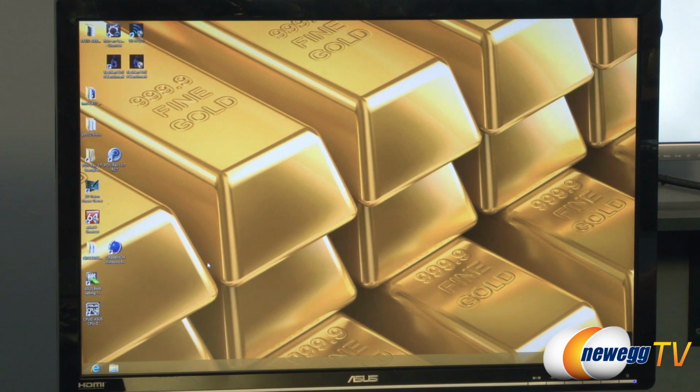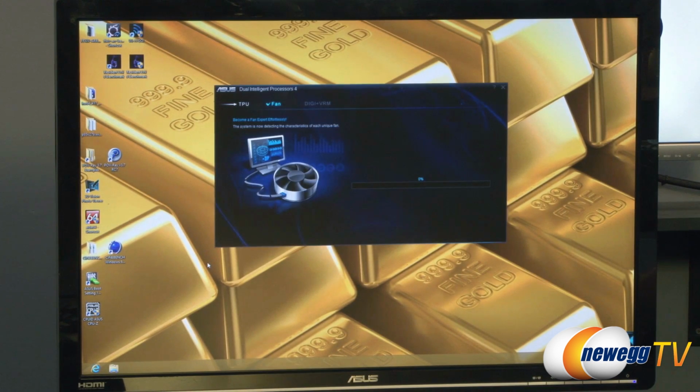Now that's a key differential. When you generally go about manually overclocking your system, most people tend to use a manual VID, which is very inefficient. It means that you have a fixed voltage, regardless of whether your CPU has the capability of dropping down in frequency and the voltage being supplied. You have people that use fixed multipliers with fixed voltages. That adds more voltage than you need, adds a higher thermal load, produces hotter, consistent ambient temperatures, and you even have a higher likelihood of thermal degradation.